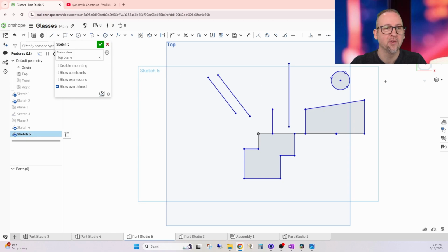If we want something to where it won't move, we can hit this fixed point right here. And then now we have just locked that in. So basically we just told this that it should be constrained and will not move from here. So you've seen it turn black. So I want to undo that. I want it to float around and be okay to float. Okay.